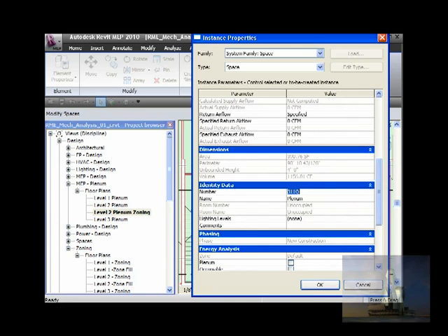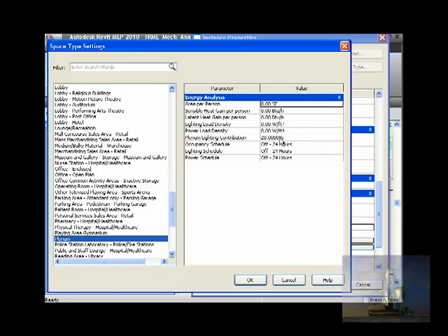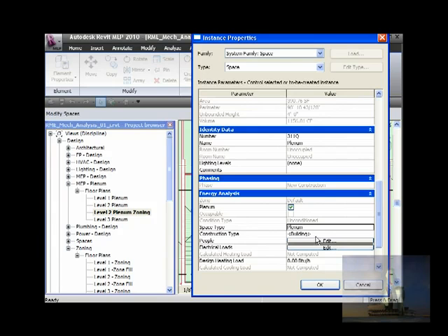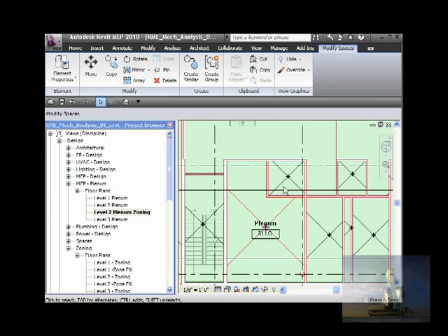I was putting the number below so I could check what it was below, and using the same room number and the same plenum, the same number, same room name and same room number. And what is important here, this is plenum space and is not occupied, and service type plenum, and construction type by building. So immediately when you choose plenum space, it changes all values.